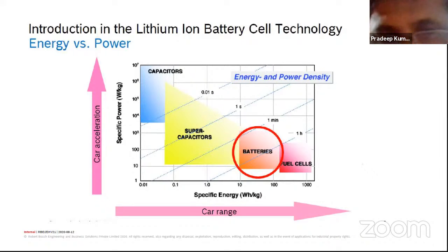So the supercapacitor will look almost like a battery, and it can charge and discharge. The advantage here is that whenever a power requirement comes, it can immediately discharge and give you that power. So you can use a combination of supercapacitor and battery in a very premium segment car, where you will get very good sporty behavior because it is able to discharge very high current, and you also get the required range because your battery is giving you specific energy. But supercapacitor plus battery will become even more costly. I think this can be affordable only in a premium segment vehicle.